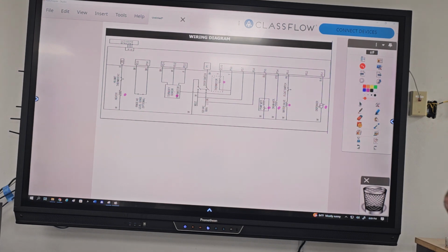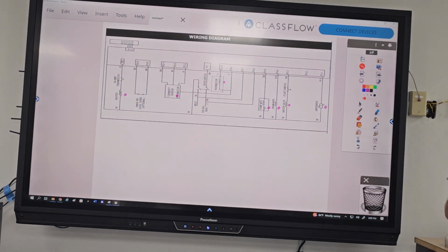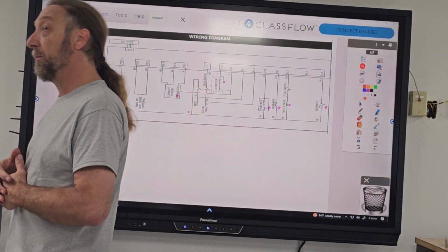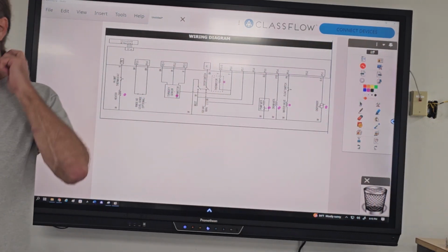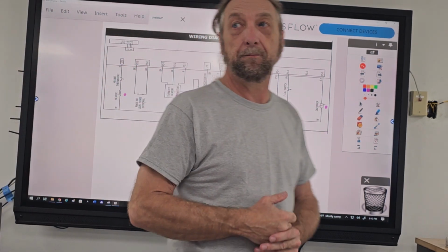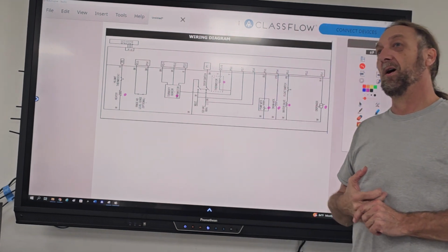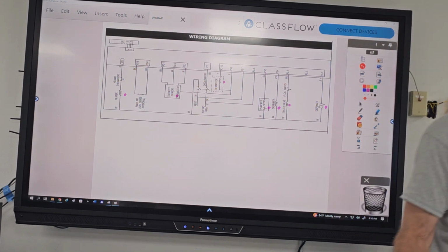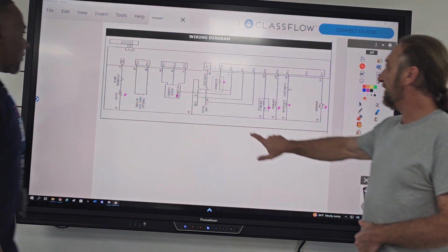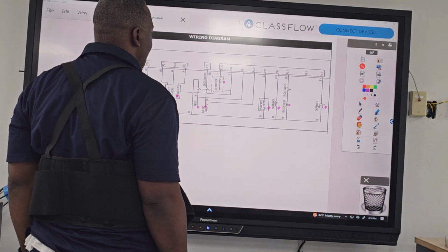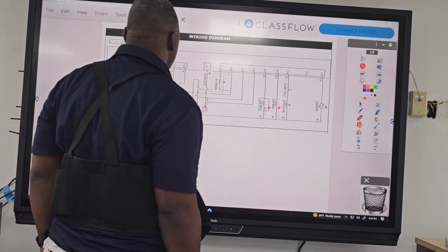So here's the thing. Let's take a look at the dispenser. Now, somebody want to come up here and highlight the circuit just for the dispenser, how power flows in, goes through the board, goes through the dispenser and back out? Someone want to try that for me? All right, sir, I got our first volunteer here. So power's going to start here on line 1 and end there, and we're going to energize the dispenser. So how is power going through the dispenser?